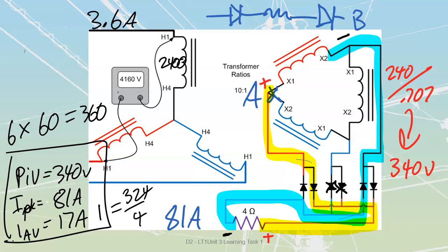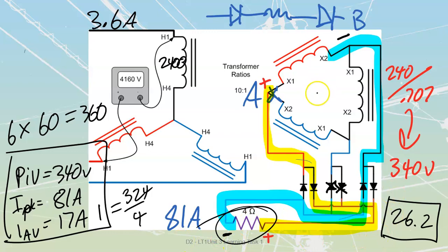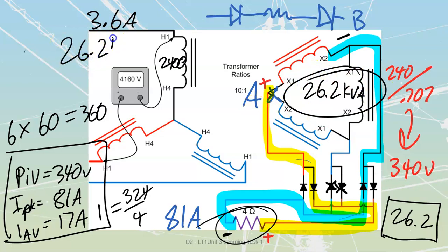We're done with them. We're going to move on to our next subject. Once again, last thing, VAN is equal to VAO. So critical because it allows us to do any other calculations. In this case, we said it was 26.2 kilowatts that we had. It's all resistive, all over here, which would mean that I'm going to have 26.2 kVA because my kilowatts and my kVA are going to be the same over here, and I can use that kVA to calculate line values of current, and 26.2 kVA over here. Just makes your life a heck of a lot easier.